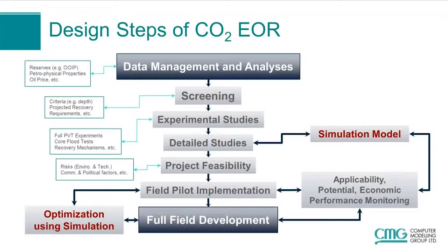This plot is showing the general approach for the application of the carbon dioxide EOR process. It has many stages. The first step is data management and analysis. The reservoir development plan depends on the ability to collect and analyze the available data, such as reserves, petrophysical properties, and oil price. The second step is screening. Effective screening practices must be employed to identify the best available candidates. So how much oil can be produced and what techniques should be applied.